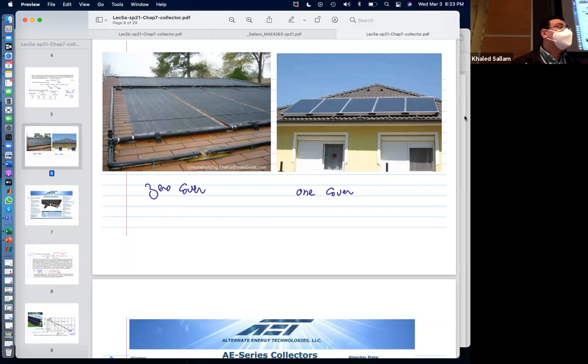Same concept. The tablet has energy generated inside, right? All this battery is running through those circuits to make calculations and do things, and it gets heated. So now how hot should it get? How hot should this tablet, here's my tablet, how hot should it get? Why does it need to get hot to start with? Because it needs to spill away that heat, right? The heat generated inside by the circuits needs to be thrown away. Thrown away to what? To T ambient that is really high. In the desert, T ambient is like 120, and the tablet needs to go to 100 and whatever so that it can spill the delta T, so that its Q, which needs to be equal to whatever is generated inside, needs to be equal to AU delta T, right?